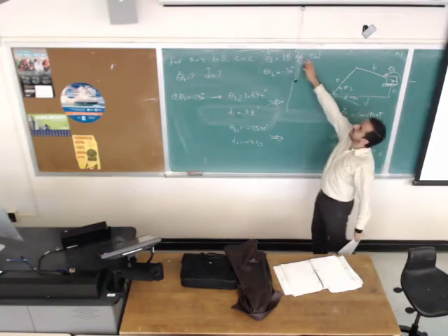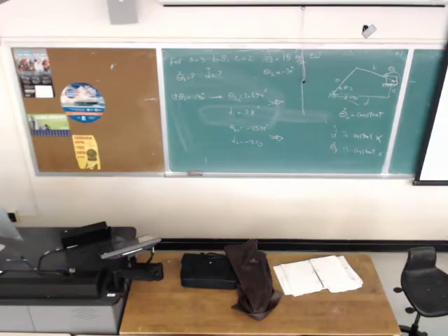Theta dot 2 is 15 radian per second clockwise, meaning I should plug in negative 15. Sine of theta 2, sine of negative 30. Second row, A is 3, theta dot 2 again is negative 15, cosine of negative 30. If I do the math for these two, I will get negative 22.5 and negative 38.97.